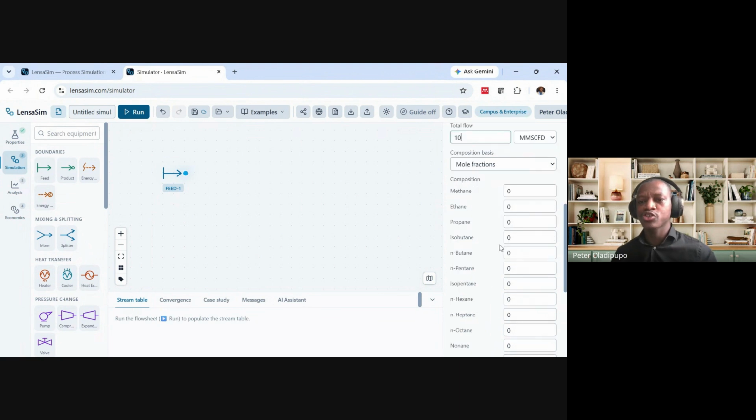And of course, the mole fractions, just as I was saying in the slide I showed for the composition. So that's maintained at methane 78.8%, ethane 10.50, propane 4.62, isobutane 0.79, and n-butane 0.97.